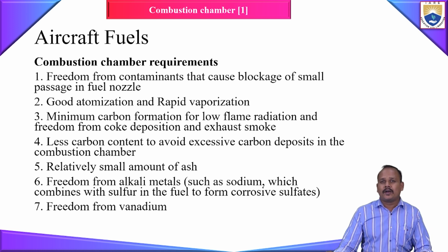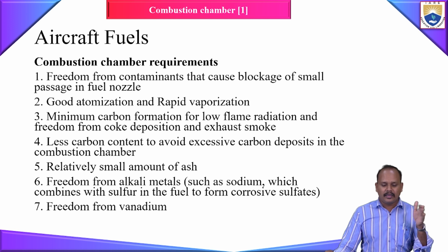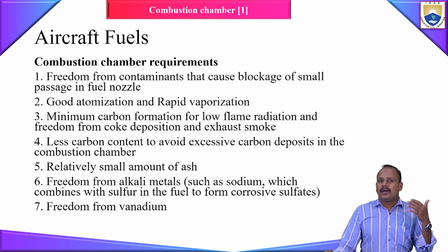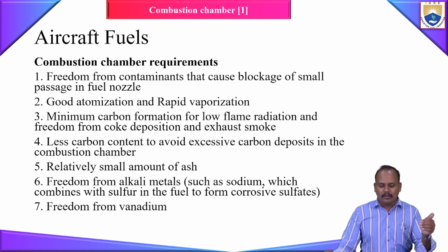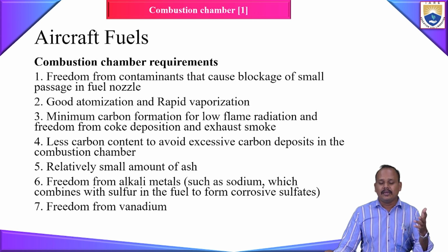Another important requirement is minimum carbon formation, that is, freedom from coke deposition. Coke is basically a layer of incomplete combustion product which is going to deposit on the combustion chamber walls. You see, we are using transpiration cooling, right? If you have coke deposition, it is going to block your inside liner walls, which is going to prevent the cooling air from coming through this porous wall, which is going to reduce the effectiveness of the cooling technique you are going to use. So obviously the fuel you are selecting should be free from coke or carbon formation.